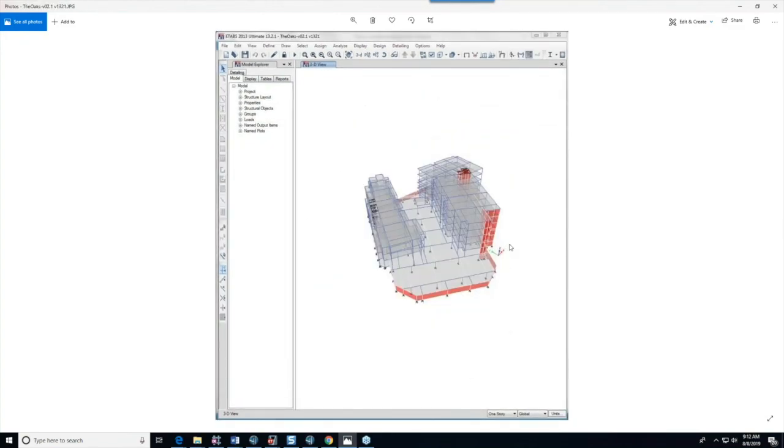It's a little bit unique, and for those of you who aren't that familiar with the ETABS program, the ETABS program will allow you to model towers independent of one another. So it could mean that you have one tower that has a number of different floors, and each of those floor elevations are really independent of an adjacent tower, all connected on the same podium.